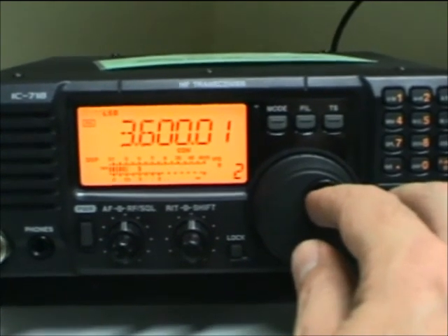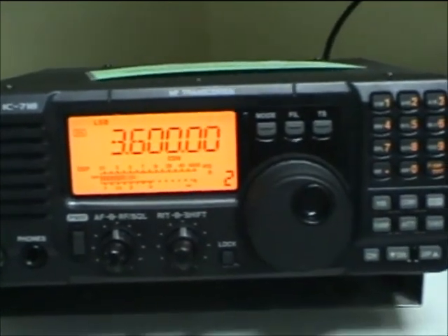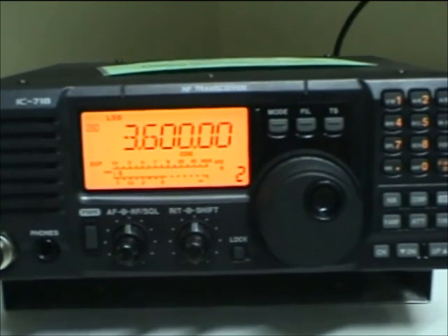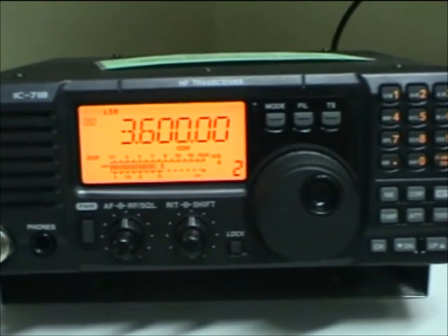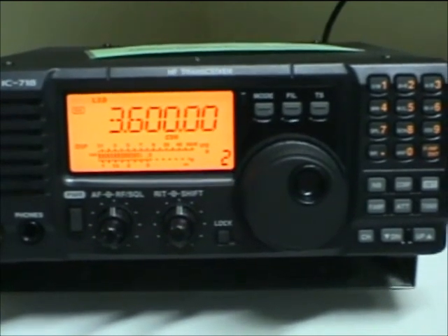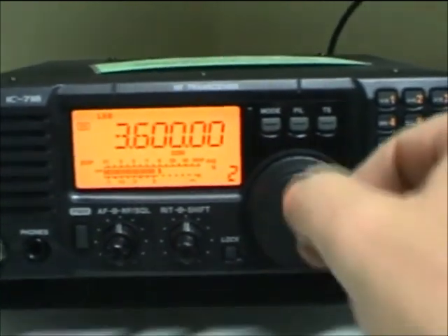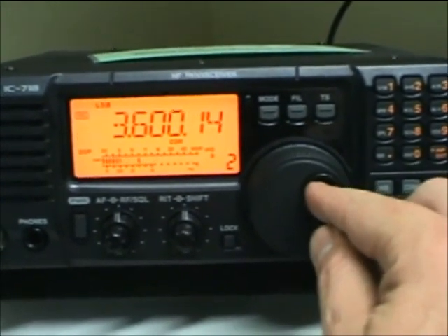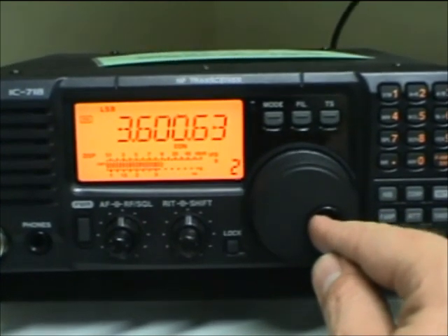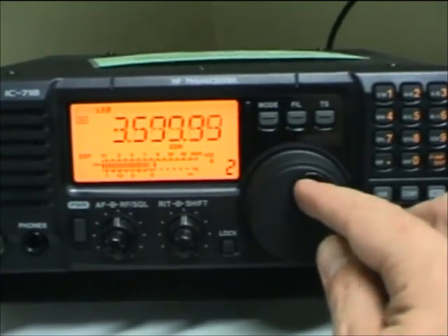Now with single sideband, as we move away from the signal coming out of the IF amplifier system into the product detector, as we tune away from it, it actually moves away from our carrier insertion oscillator or BFO frequency. So the speech gets shifted in frequency as well, and you'll hear it having this effect here. So we've shifted the whole range of frequencies up. If we tune the other way, it goes down.